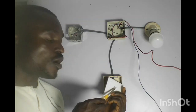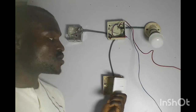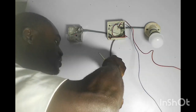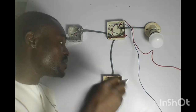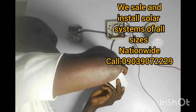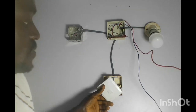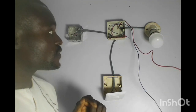Whether your switch is going to be on this way or this way. So I usually put it at L1 so that it will align with how the switch is being made. Everything will align very well. So the next thing I'm going to do is to connect this second wire to L1. I've connected this. My switch connection is complete. So I've connected these two wires at the other end of the switch.